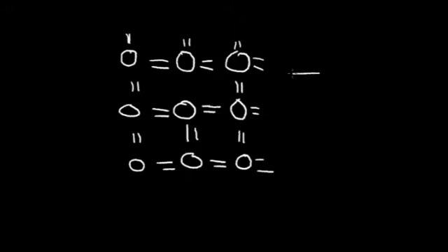For example, if we apply an E field and try and make the charge move, try and generate a current, not much happens. It's a very stable structure. It's a very good insulator, or at least at normal temperatures. If it gets extremely hot, then it can become a conductor. But we can add impurities into this crystalline structure, and we can create 2 different types of silicon. We can create what is called a P-type silicon and what is called an N-type silicon.